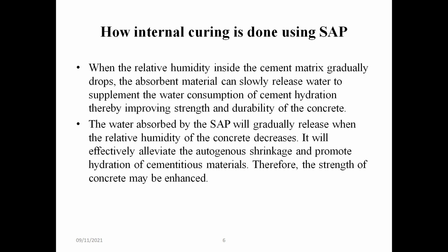How internal curing is done using SAP. As told earlier, concrete contains voids. Now these voids are also classified into two categories, macropores and micropores. Our main area of interest or study is macropores because these macropore sizes range from centimeter to micrometer. So now we are actually trying to incorporate the SAP into these macropores.